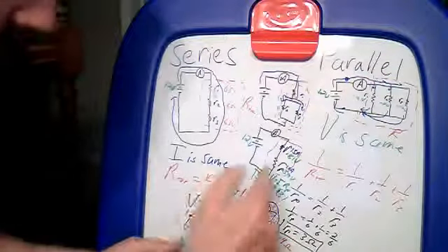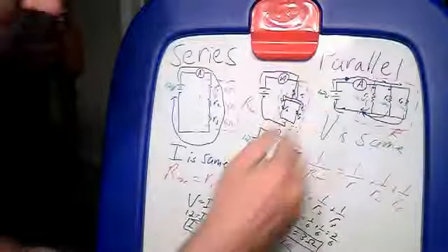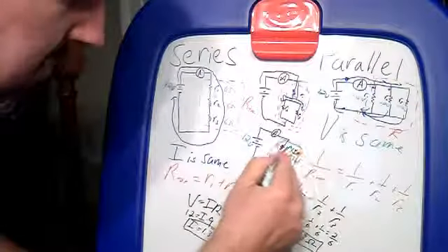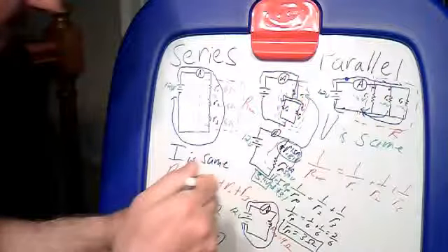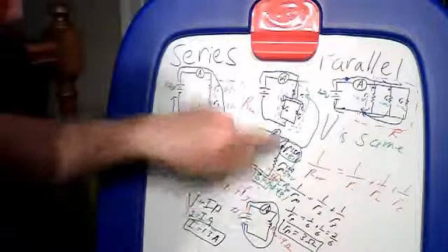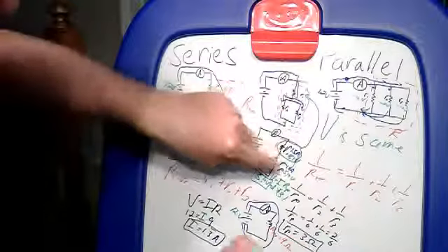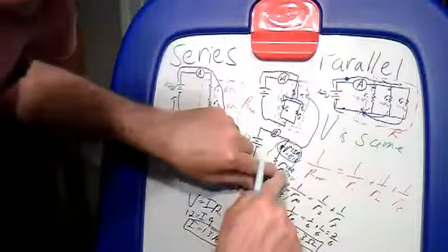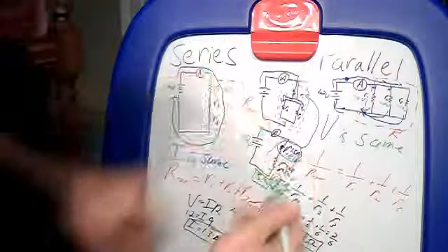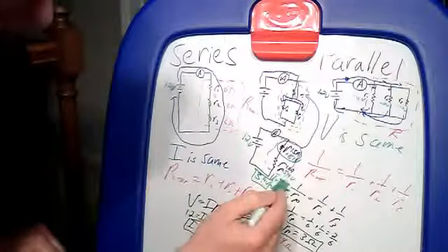So now we go back up a level. R1, we're already done, because that doesn't change. All the stuff that's true here is also true right there. But RP is really these things. And we know the current for RP, we know the voltage for R3 or RP. But really they're parallel, and the current's not the same, but the voltage is.